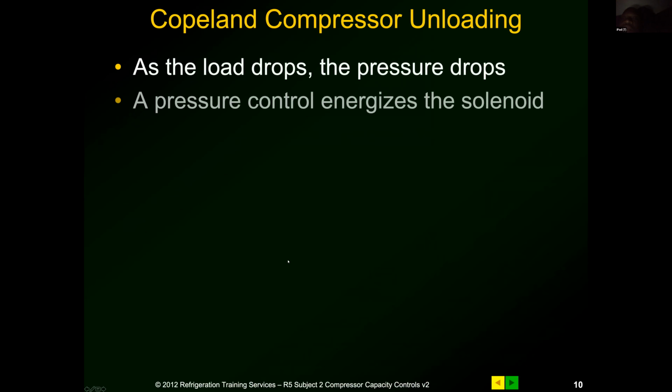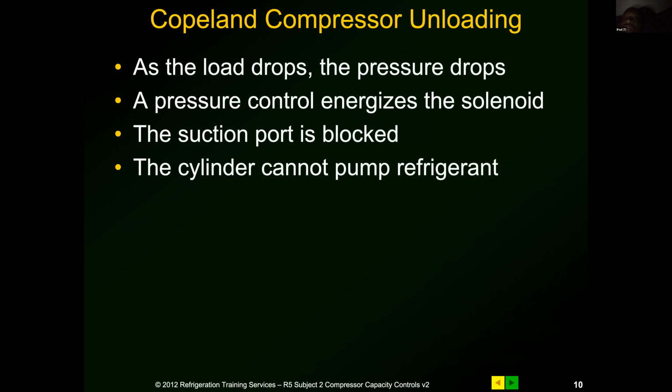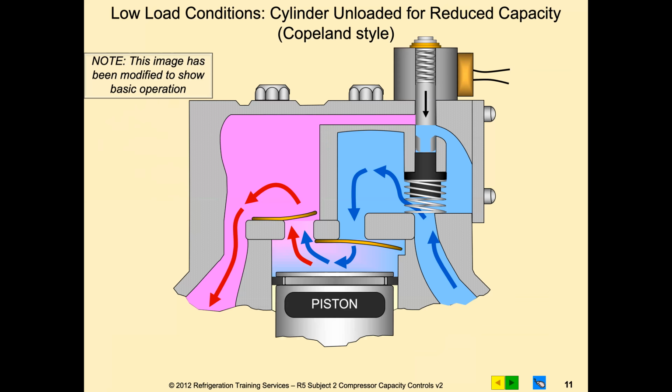I have one question. Yeah. When that solenoid valve de-energizes, it pushes that spring down on that black part to close that suction line off. It closes off that suction line right there from vapor going into that piston.